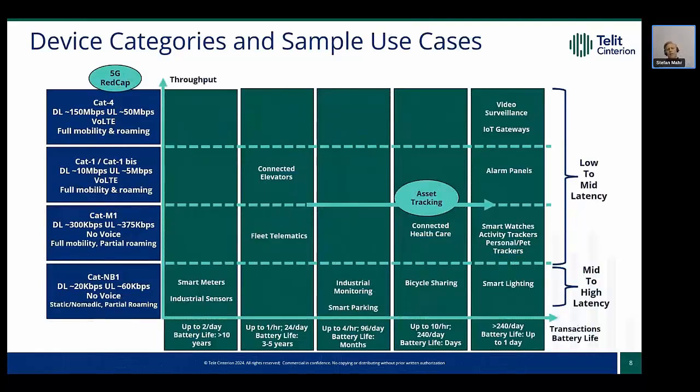So what we just discussed, both Cat-M and LTE Cat1 are good choices for trackers. And most of the devices are going to use this standard, as you see here in the middle of the slide. But there are other options with different data throughput, different latency, different reaction time in the network, and different power consumption. NB-IoT, for example, you may pick as the lowest tier option here. It's maybe good for simple, low-cost, small battery-operated asset trackers with limited mobility.